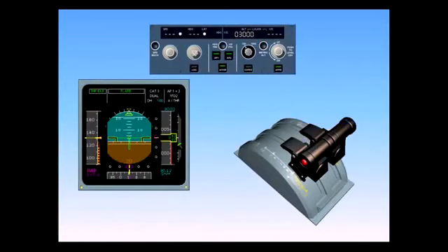When the thrust levers are set to idle, the autothrottle system is automatically disengaged. On the FMA, A/THR in white is extinguished. The FMA autothrottle column is blank, and on the flight control unit, the autothrottle push button is now extinguished.